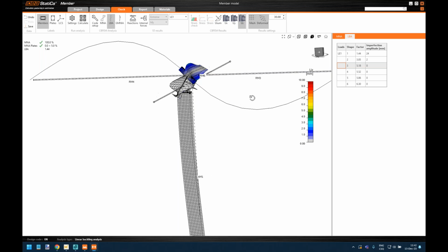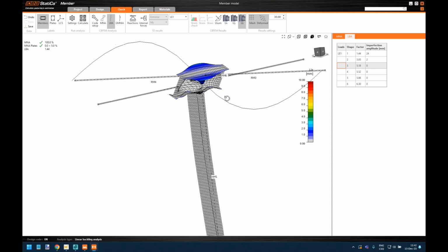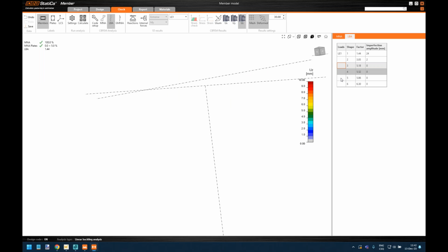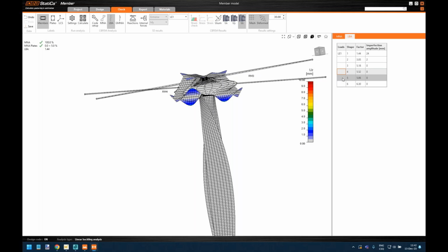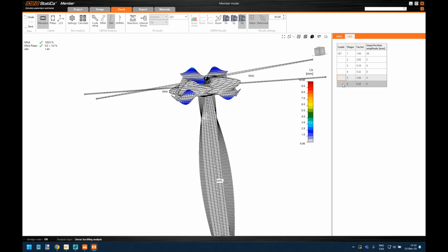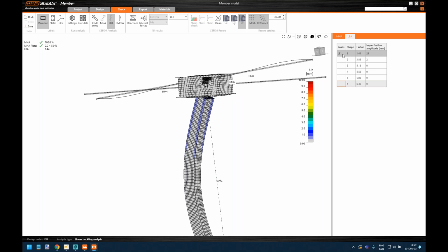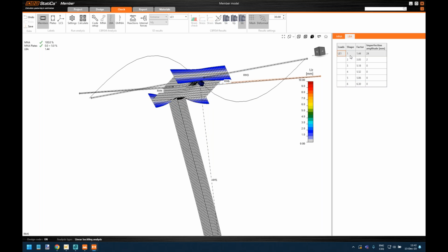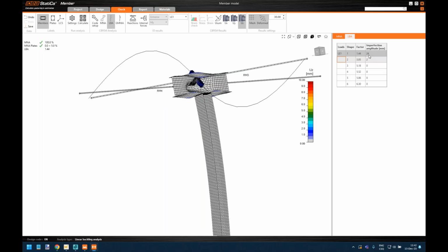And these are more buckling shapes. And by checking them and considering them, we can basically say this would not happen at the same time as the first one. So the first one usually is the most dangerous and the one that could happen. Second one, sometimes if it's a local buckling, can happen together with the first one.